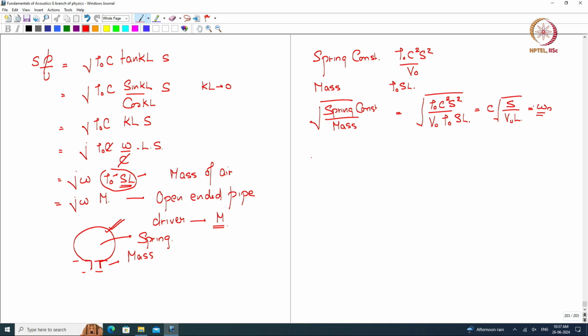Okay. Now, if there is a room where there is an offending frequency omega n, if we can put in a tuned Helmholtz resonator, which is typically small in dimensions, I am just exaggerating, and you tune the S, V0 and L values so that the resonant frequency of the Helmholtz resonator is omega n, then you will be amazed that a lot of interaction will happen close to or in the Helmholtz resonator.